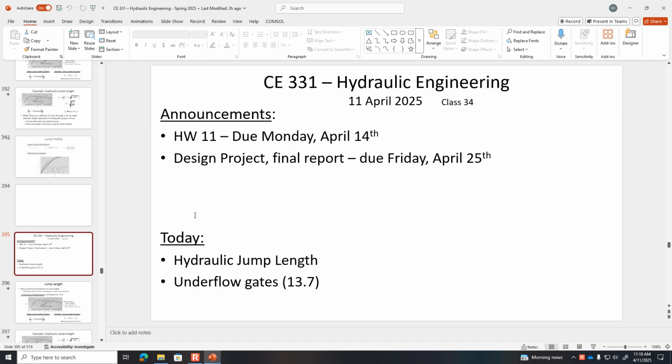So as we were back in the hydraulics lab just now, and we were leaving, Ethan made the observation that it wasn't just a single depth over that broad crested weir, that it was gradually getting shallower and shallower the closer you got to the end. And that's because the drop-off, the water's accelerating as it approaches that drop-off. And so we have gradually varying flow as it does that.